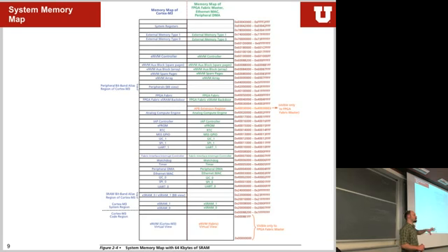Oftentimes they make the register maps such that you always have to write into something to clear a bit, or you read a bit to actually get the status out. You will see about it. Sometimes you have 3 registers to do operations on more or less the same background register that they're actually using. So exactly for this case, if you want to clear one particular bit, you write it to one memory location. If you want to set one particular bit, you can write into a different memory location without having to change or touch or read out that particular register. Did that make sense, what I just said? So if not, it's a very important concept.